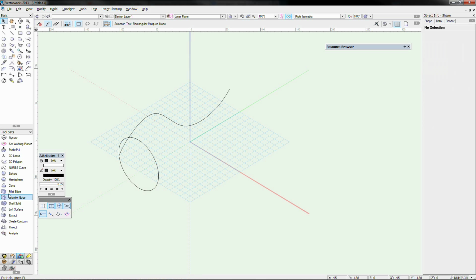And what we've got here, when you look at the loft surface, is that when you click on this second mode, it says that you need one rail, so you need a rail, and then you need profile curves. And what we're going to use is this as the rail, and this is the profile curve. Just think of this as a train following a set of train tracks. So it says select the rail curve first, which is this one here. This is our rail, so I've left clicked on that. And then we want to select our profile curve, which is this circle.